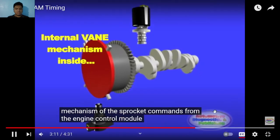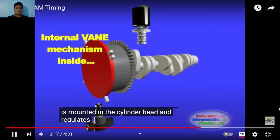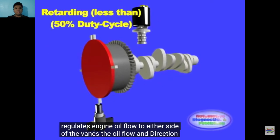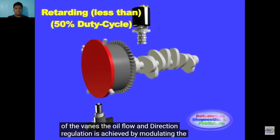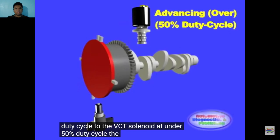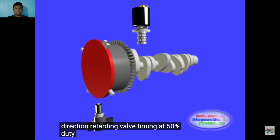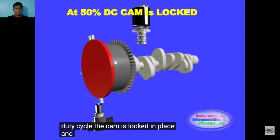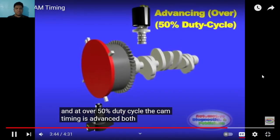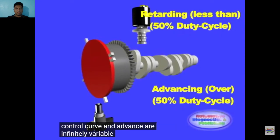Commands from the engine control module adjust the position of the oil control valve, which is mounted in the cylinder head, and regulates engine oil flow to either side of the vanes. The oil flow and direction regulation is achieved by modulating the duty cycle to the VCT solenoid. At under 50% duty cycle, the oil flows in one direction, retarding valve timing. At 50% duty cycle, the cam is locked in place. And at over 50% duty cycle, the cam timing is advanced. Both sides of the control curve, retard and advance, are infinitely variable.